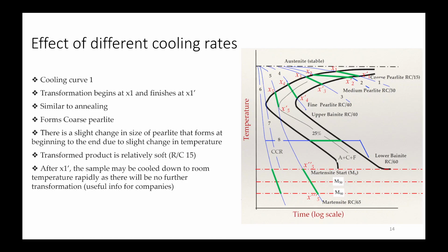The point about that electronegativity difference is higher. Is it actually decreasing due to the formation of compound? Electronegativity is reducing. I mean, the greater the electronegativity difference, the solubility will be lower. Yes, the statement is right. If the solubility is getting lower, since when the electronegativity difference is higher, then they will likely form compounds instead of forming a solid solution.